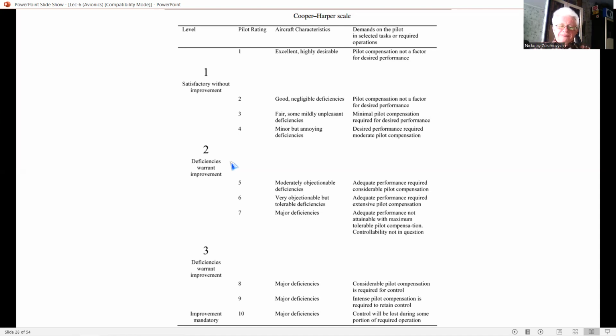The original Wright Flyer was susceptible to PIOs. In conventional and augmented aircraft, PIOs have generally been due to design deficiencies such as low damping of the short period pitch mode, or low control sensitivity, meaning stick force per g.